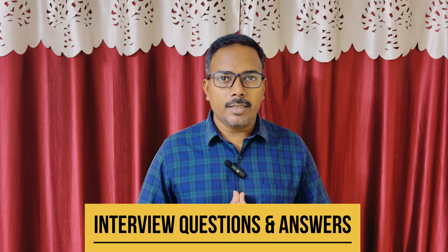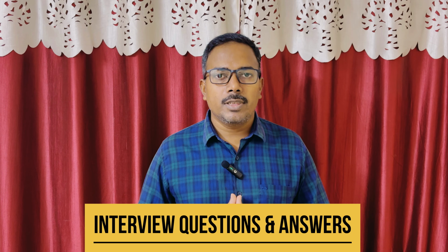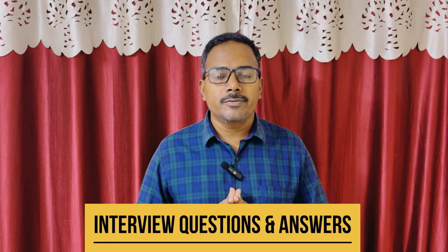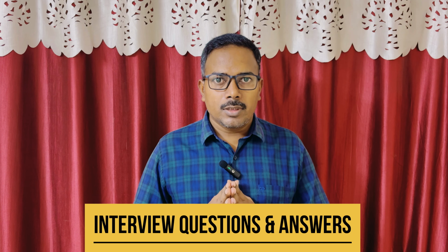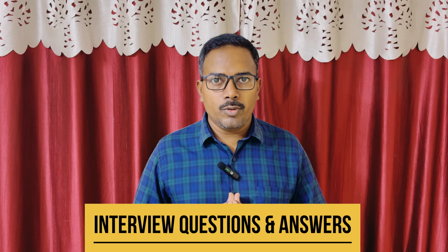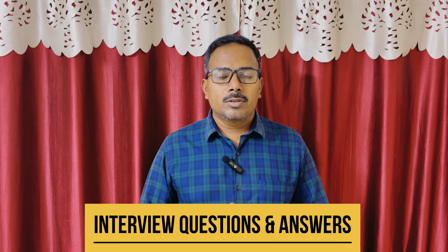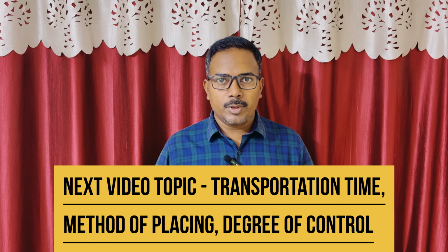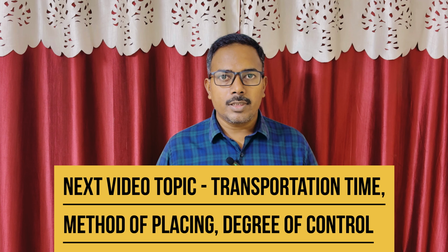We have come to the end of this video. So we will see some interview questions and answers. The question is: how does low slump concrete work with vibration? Because the vibration temporarily reduces the friction between particles, which allows concrete to flow, expel air and fully compact despite low slump. Our next video topic is transportation time, method of placing and degree of site control.